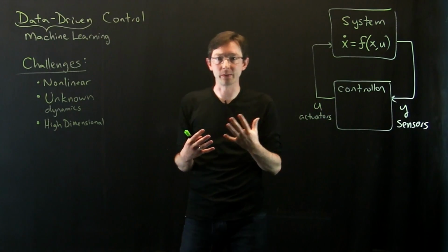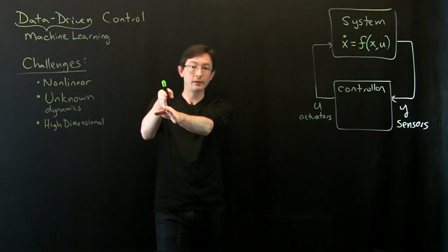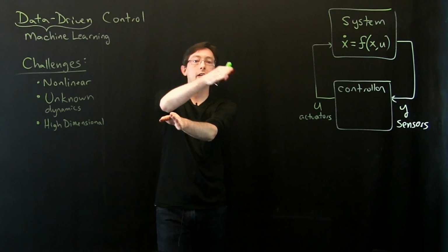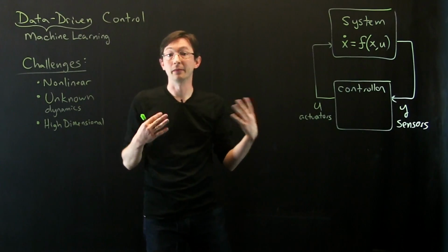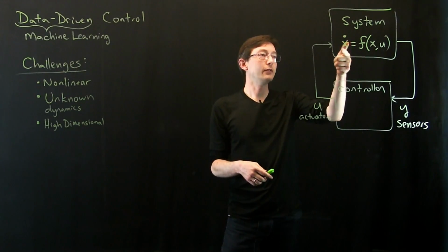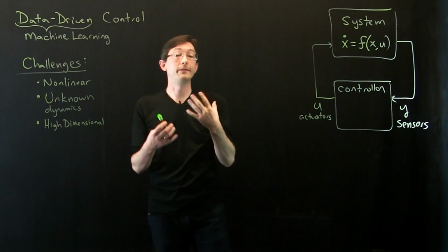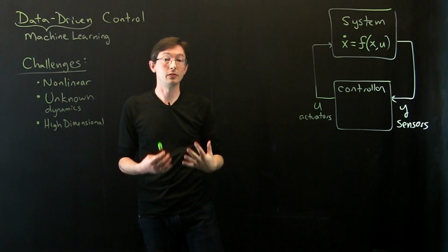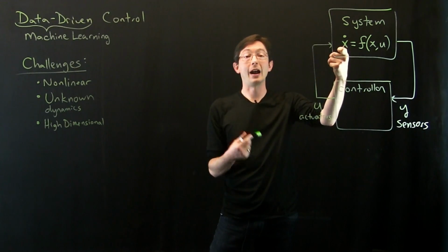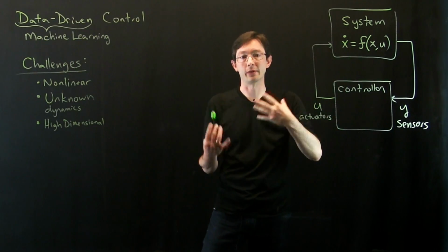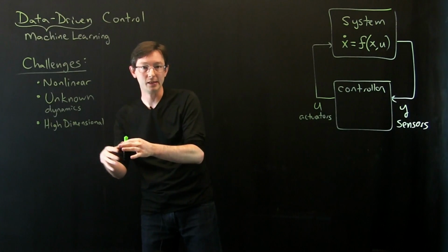Similarly with turbulence, even though there are millions of individual vortices, if I have a wing that's stalled, there are going to be large coherent structures that are the most important for lift and drag and mixing and things like that. So even in this million or billion dimensional state space X, there might be a few numbers, some low dimensional representations, some dominant coherent patterns in the data that are actually what I want to control. They're proxies for what I actually want to control, which might be lift or drag or suppressing disease.